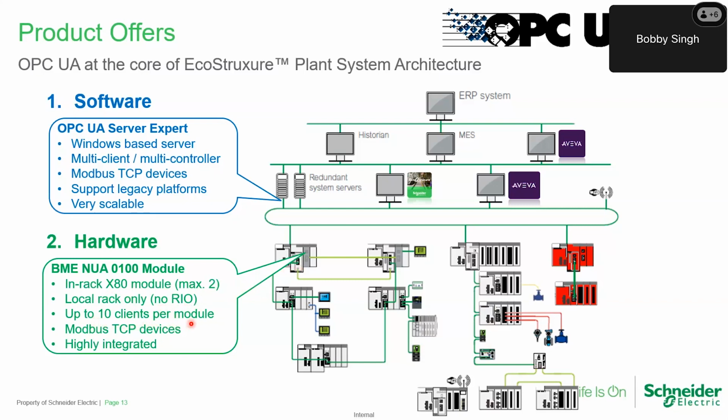If you need more than 10, you will need 2 modules. The hardware solution simplifies integration with SCADA applications since there is no need to install any additional software nor a license. You can easily manage it with a built-in web server. Also, when using the hardware-based OPC solution, now you have secure and encrypted communications directly into your PLC.